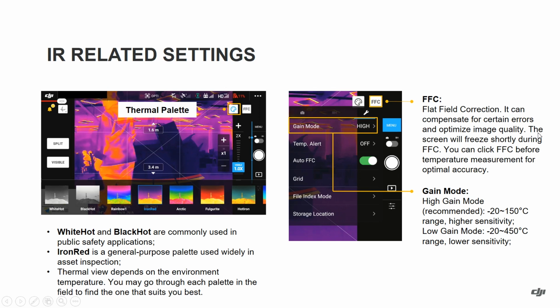And when you press the FFC button, you will find that the screen will freeze for a short time during this correction, so you can click FFC each time before the temperature measurement for the optimal accuracy.